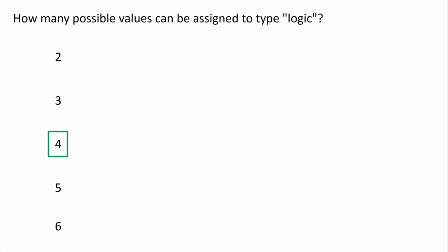It can be synthesized, right? So when you talk about logic, what is logic meant to be? Well, that's meant to be a binary value, 0 or 1, right? So basically it's 0 or 1. But there's some additional values that it can take. Well, there's a Z potentially, which is high impedance. Now, the question there is, if you have it declared as a logic and not a tri, can you assign Z?